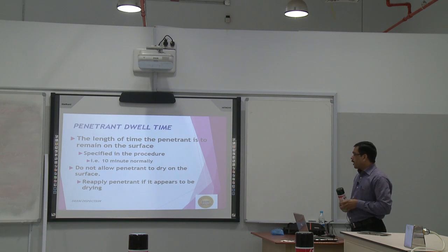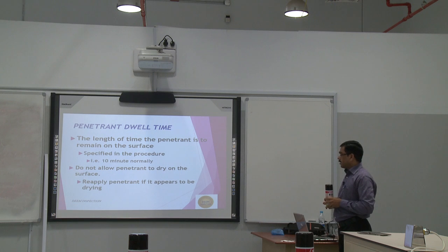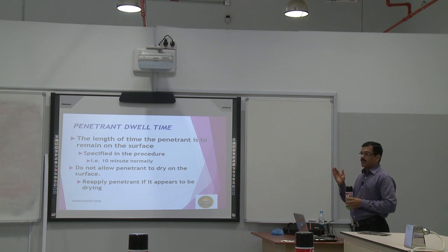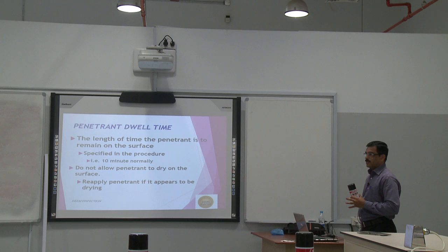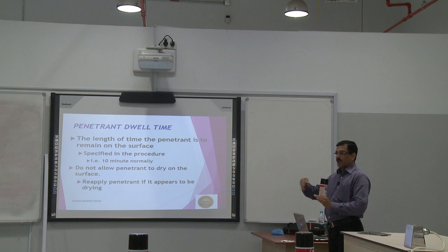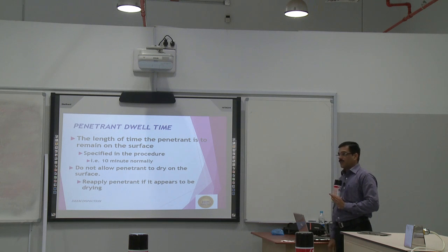And do not allow the penetrant to dry on the surface. If it appears to be drying, we will reapply the penetrant. Suppose the time given is more than 20 or 30 minutes, don't allow it to dry; we will apply the penetrant once more and keep it wet. For reapplication, do we have to clean the first layer first? No. On the same layer we can apply, only a light layer, just to keep the wettability. Yes, keep it wet.